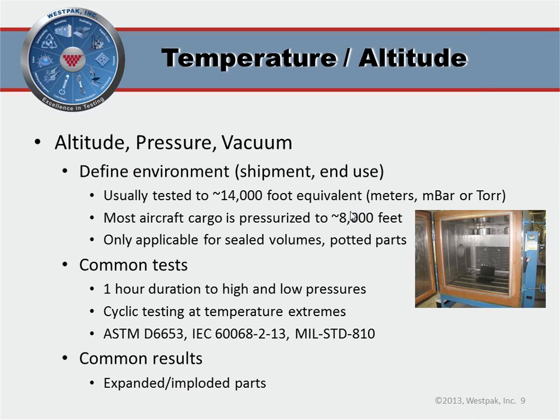Units are usually in elevation equivalents of either feet or meters. Sometimes things are specified in millibar or torr. Aircraft cargo today is actually pressurized for the most part to approximately 8,000 feet, as are passenger aircraft. So believe it or not, aircraft shipment is not the biggest pressure hazard that most things will see.